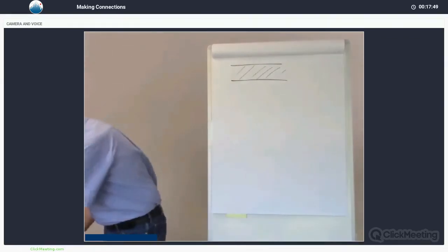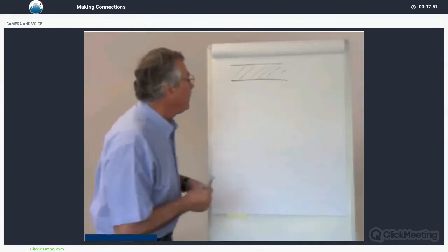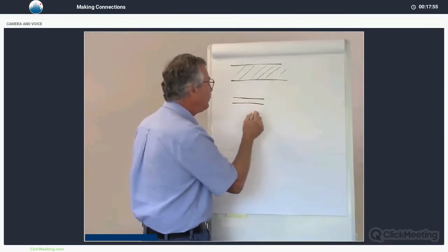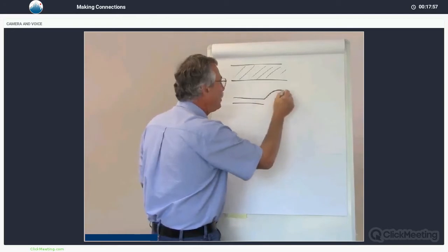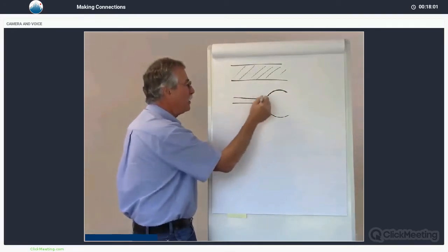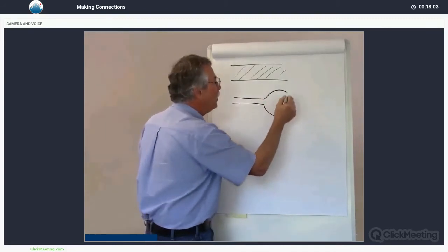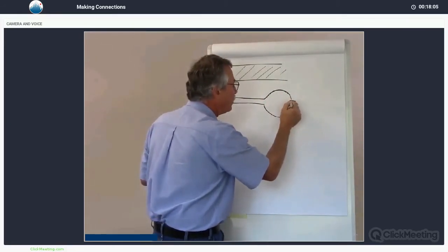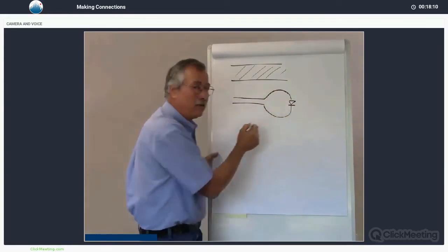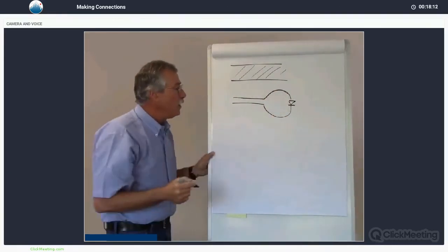That brings up another issue, incidentally. Imagine that we have this nice flat strip line and we make a big loop at the end of it. And we're looking at the strip line from the edge. These are my two conductors. If we make a loop in order to connect it to our laser diode, what have we done? We've just created an inductor, a one-loop inductor.